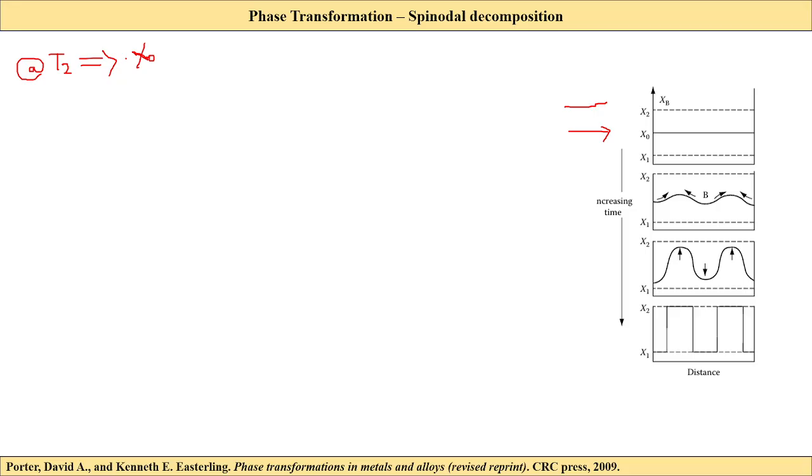Once we have different lattice parameters, at a coherent interface, going back to the interfaces chapter, where we have seen that if the two phases have different crystal structures or the same crystal structure, and they try to maintain the continuity from grain 1 to grain 2, they need to have a comparable lattice parameter, right?